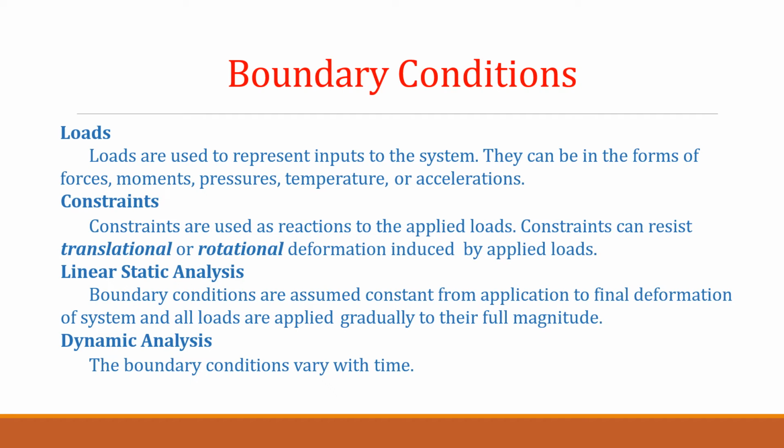Then the analysis is going to be linear static or dynamic analysis. Loads are used to represent input to the system in the form of forces, pressure, moment, temperature or acceleration. The constraints which we are using here are reactions applied to the loads, and these kinds of constraints can resist translational or rotational deformation induced by the applied loads.